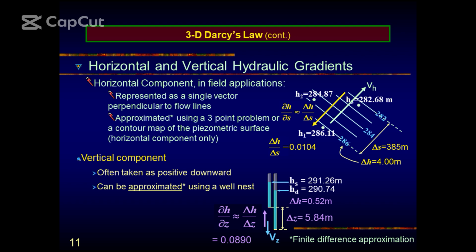You said there is a condition for the free surface to coincide with the water table. More often than not, they don't coincide. The phreatic surface is the level of water in the piezometer. Then this is the water table. Because the capillary fringe is so small, its height depends on the grain size. If the grain size is like in clay, it could be higher.